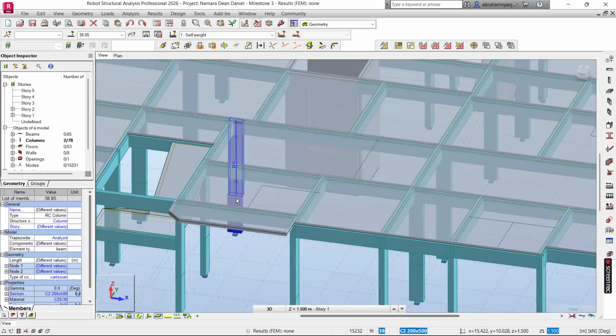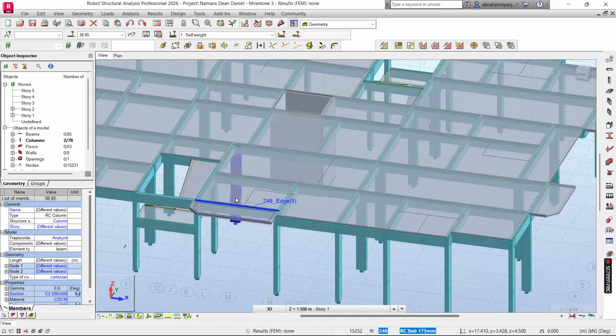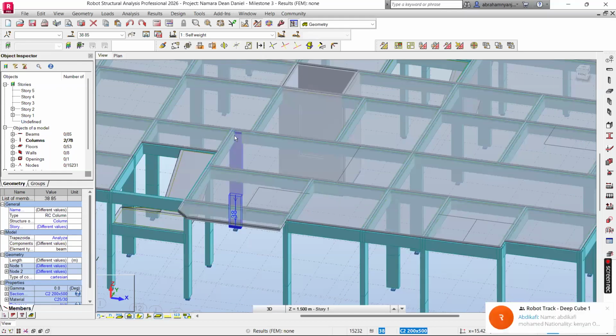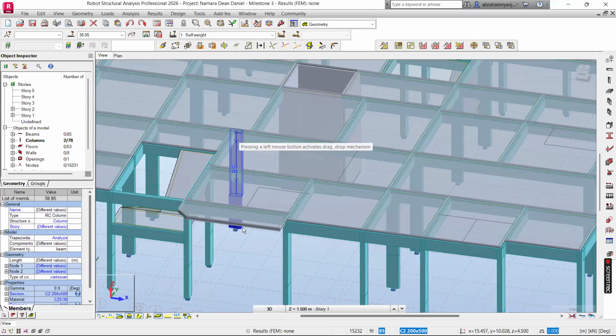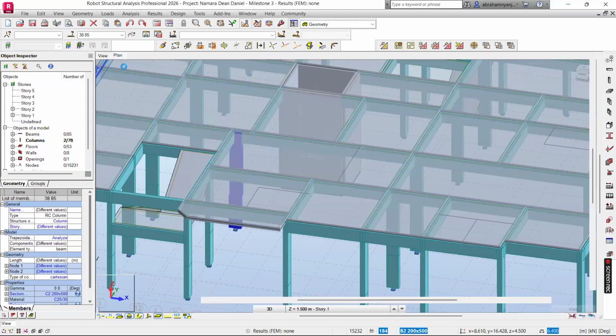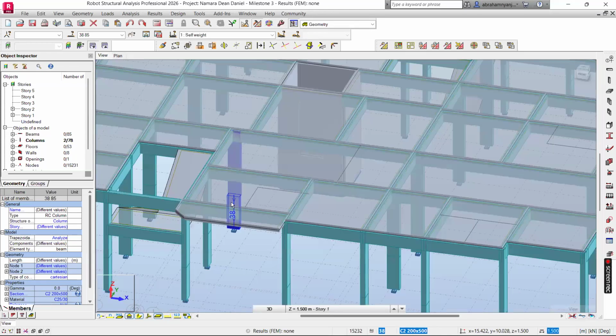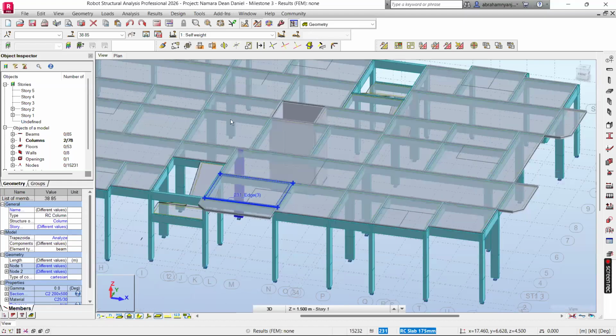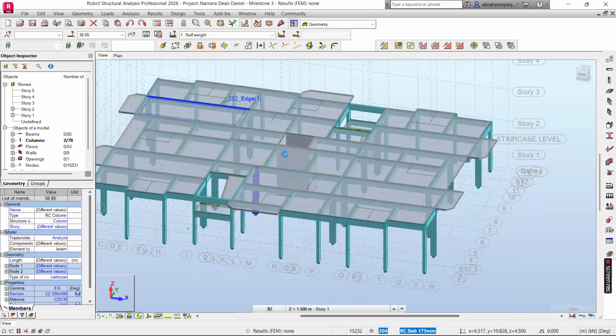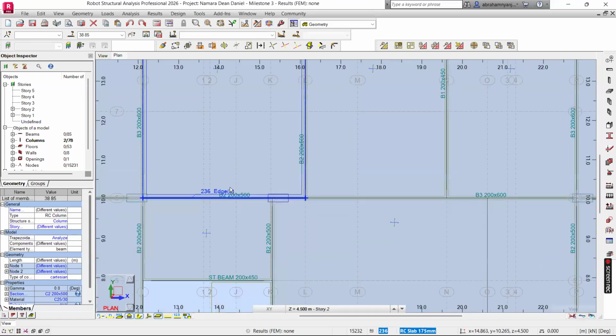So if you're moving things and you have another floor with elements, make sure you select the entire column from the level at which you are. The entire column should be selected before you move. Because I'm thinking what happened here, you moved the one above and left a portion of the one below. Yeah, but that is the fastest way that you could get to adjust this.